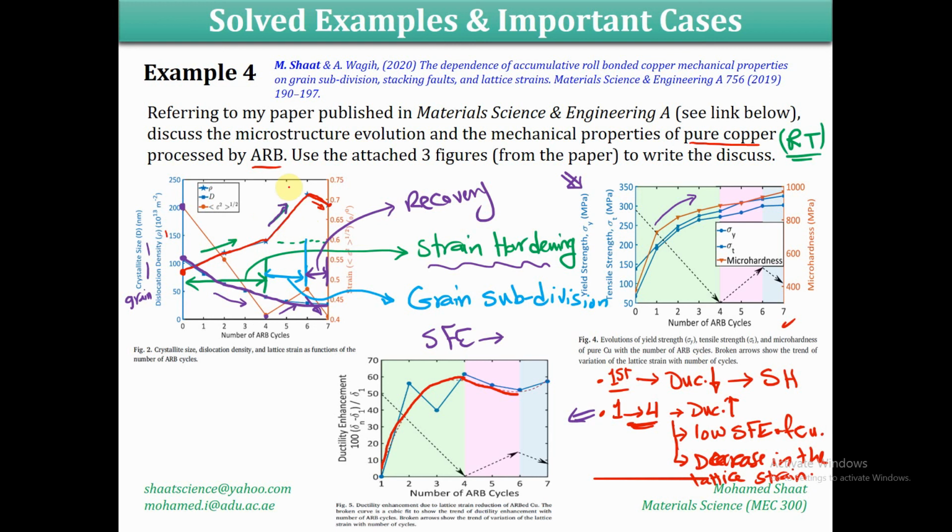They are forming within this figure, as observed here, and this results in an increase in the lattice strain. So there is more overlapping. This indicates that the dislocations within this region are more overlapping together, and they are going to impede each other, and impede the motion and the rotation of the grains inside the material microstructure, indicating a decrease in the ductility. And this explains the ductility within the second region.